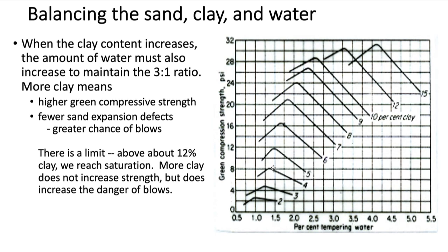Depending on if we did the lab right and have the right composition of clay, then you should get a peak, and then we try to bridge that. It may or may not have worked depending on which year you're doing this in. This last year we were only at 5%, so we ended up being way off here, in fact off the graph a little bit, and had pretty low compressive strengths. Sometimes we get into the 16 and the 20s once we're up into this 7 or 8% of clay. So again, about a 3-to-1 ratio of clay to water.